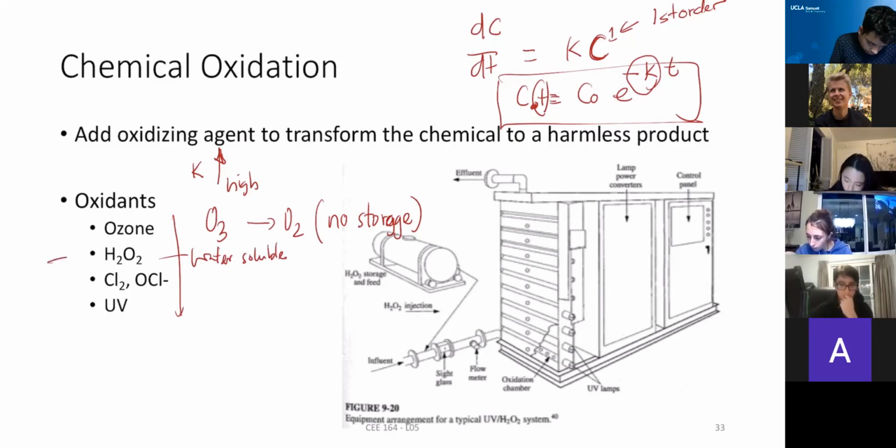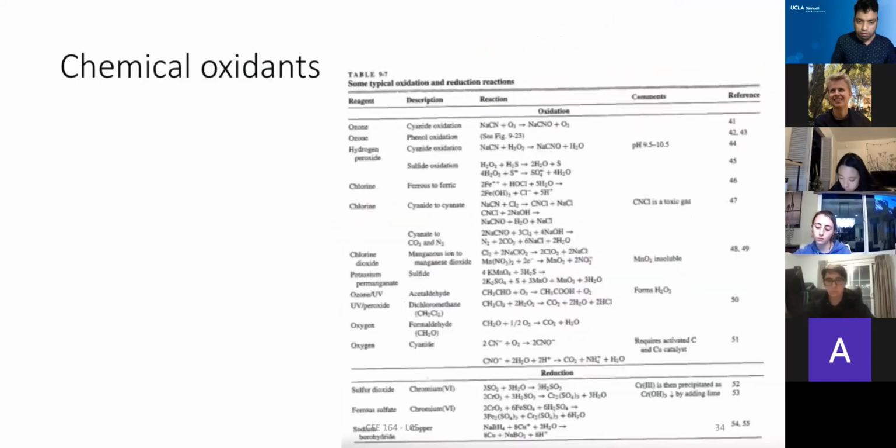So you will use hydrogen peroxide when you need easy mixing. If you have water-soluble pollutants, they are most likely effectively degraded by hydrogen peroxide because you can reach everything together. Chlorine gas, again, is not easy to mix. It's a gas, so there is always difficulty. But if you convert that to OCl, which is the bleach, then it will be effective. So these are the different advantages and disadvantages you have to think of, and those will determine what to use. But everything else is much more simplified versions.